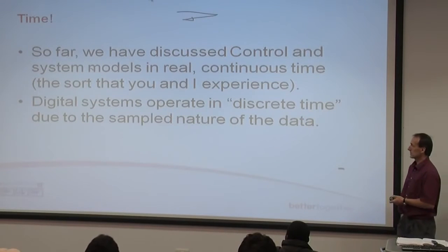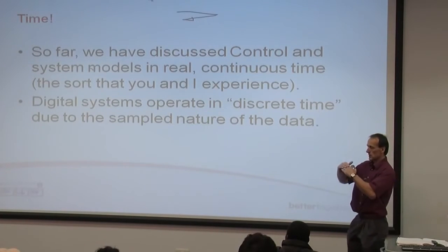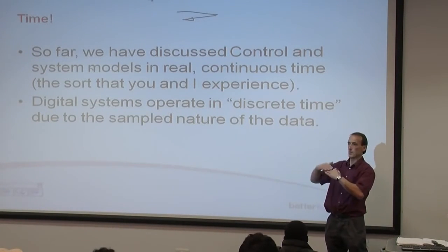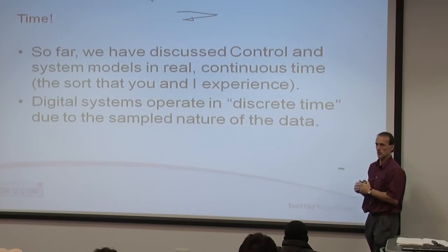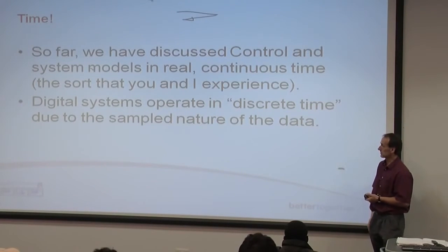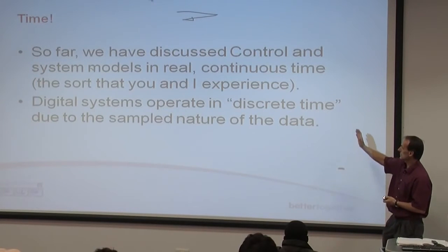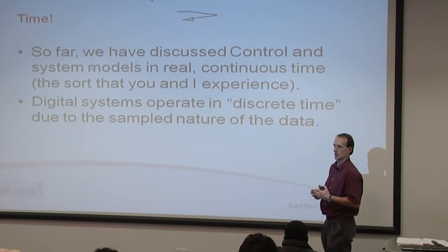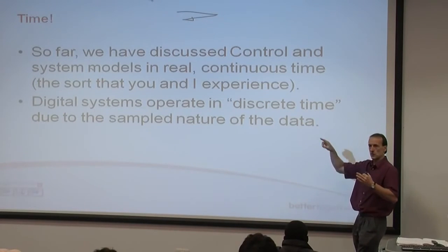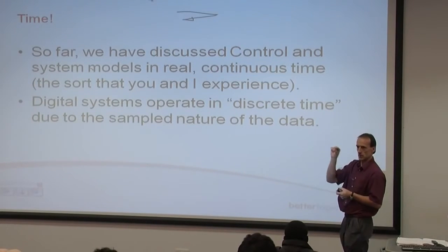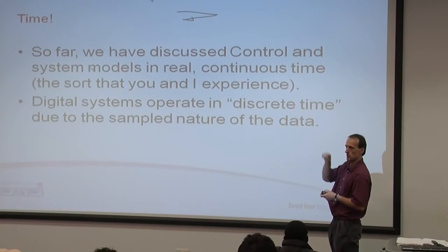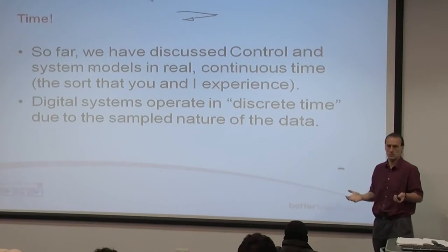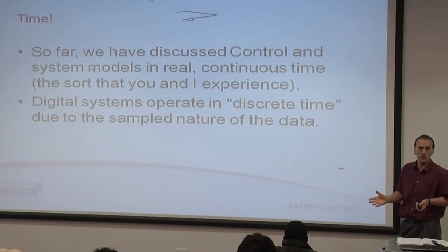One of the drawbacks of the digital system is that as well as being discrete in an amplitude sense, you can only go in steps in a digital representation, we've also got discrete time. We've got sampled data. So instead of having nice smooth curves on our data graphs, we get this collection of lollipop sticks. There's spots every so many, well, it depends how often you're sampling really.